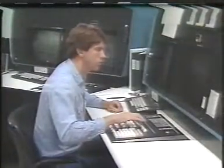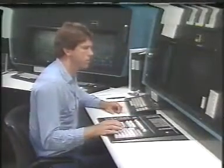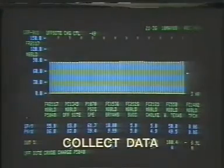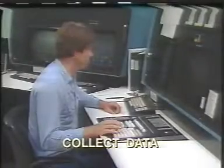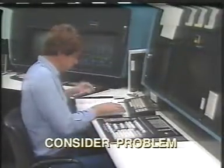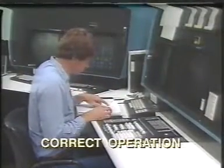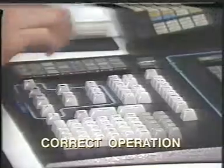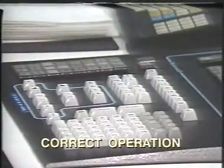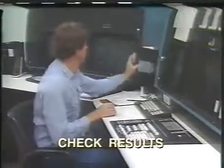When we say an operator should use logical thinking, we mean he should go through the following steps when working with a distillation column. The first thing he does is collect all relevant data on tower operating variables. Then he analyzes this data to determine if there is an operating problem. If so, he considers all the different ways it can be corrected, chooses the best solution, and makes the necessary adjustment. Finally, he checks the results of his action to make sure the problem has been resolved.